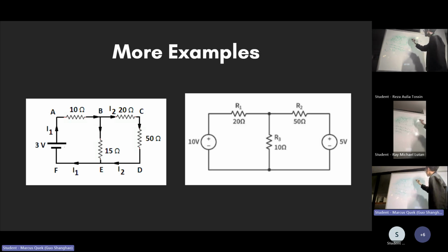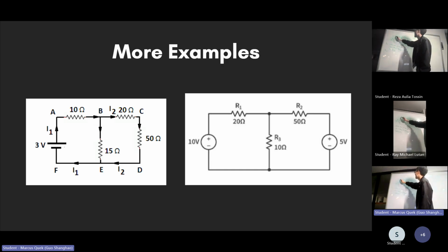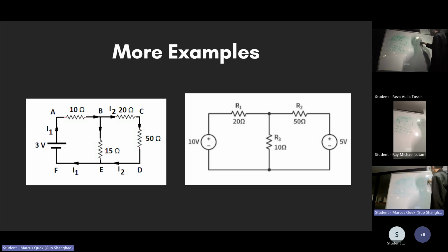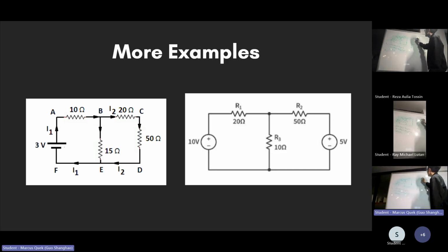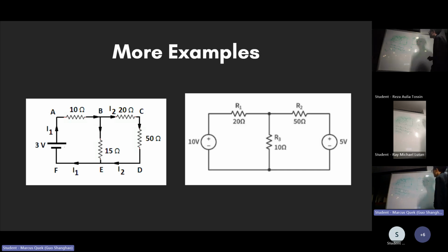Okay, so here's what I taught you: when current flows this way, you're supposed to put plus minus here, but you have to retain the signs here because you already assigned them. In fact, you can assign any arbitrary sign if you want, but you are assigning yourself a convention which you need to follow for the rest of the problem. If you change convention halfway, everything is cooked. You decide what's positive and what's negative. Yes, correct.